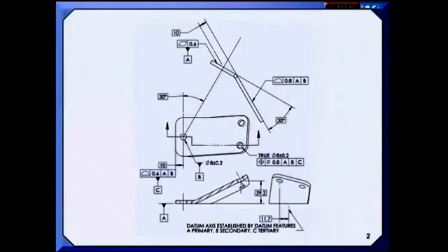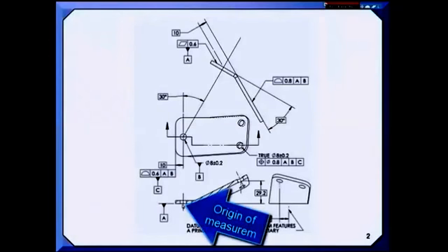I see a lot of people locating holes that are at compound angles by locating one point or one end of the hole in space using 3 dimensions, and we see that on this drawing. First, let's check out our datum features. Here's datum feature A, and datum feature B is the hole, and then C stops the rotation, so that gives us our origin right here.